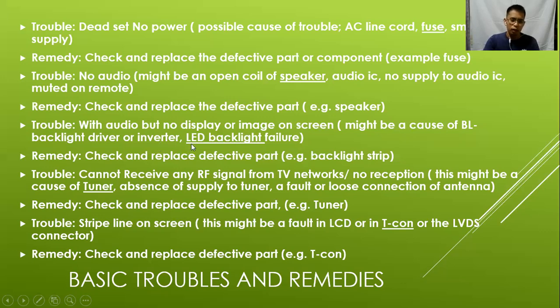Pwede rin po na maging cause ang LED backlight failure. So ang strip ng LED backlight ay series connection. There are parallel and series connections. So isa lang mapundi doon, the entire strip of backlight will not work anymore.